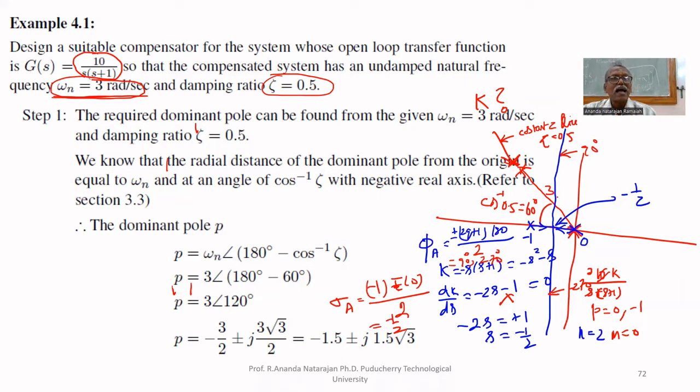Here also the asymptote and the root locus lie one over the other. That's why there is no separate asymptote for a second order system; normally it overlaps the root locus, because the asymptote is on the root locus. But the root locus is not passing through the desired point.